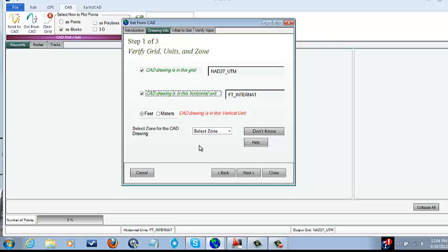If you have already brought the points in from the GPS, and you're just getting some changes from the drawing to send back into the field, then you can use the zone that was calculated at that time. However, if you don't have that information, you will need to find a latitude and longitude of some point within the drawing.